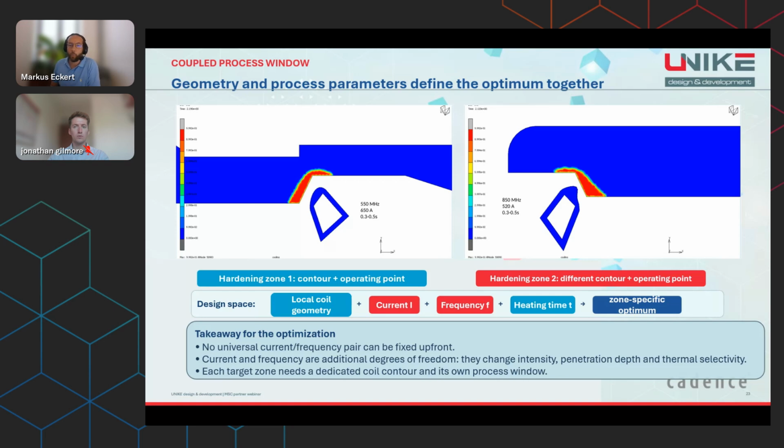We cannot define one current level and one frequency and assume that these parameters are simultaneously optimal for all hardening zones. Different locations may require different local geometries in order to heat exactly the intended regions.